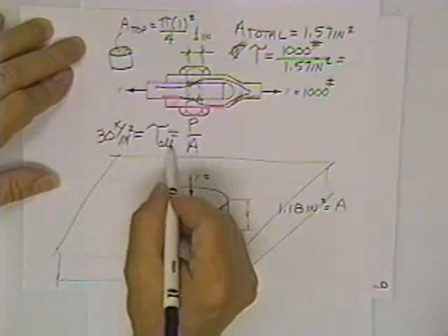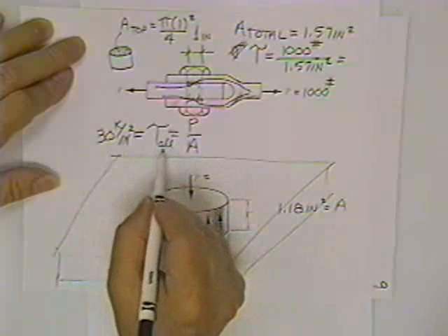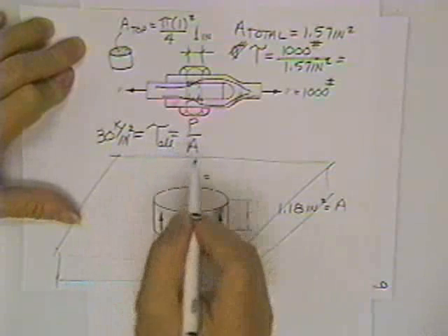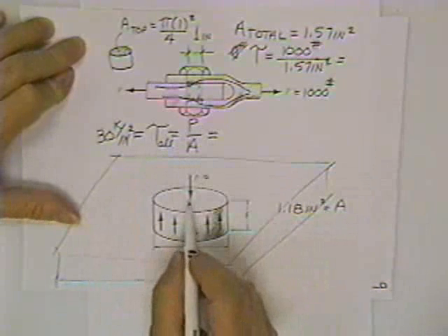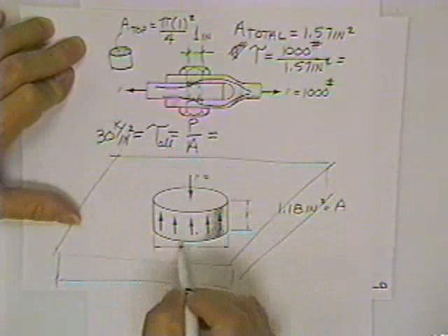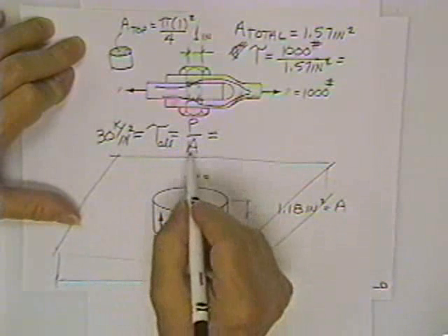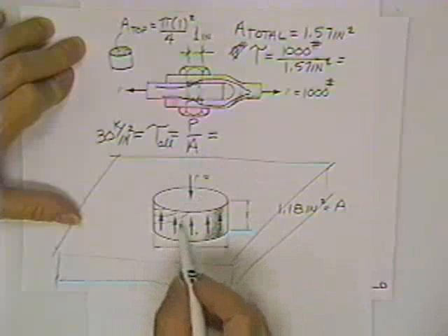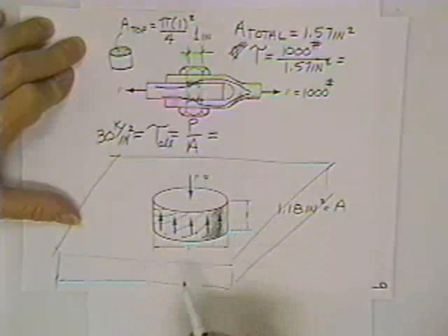Then I would put that allowed value or that failure value in my equation. The stress is load over area. I was asked how much load it took to punch this hole in the plate. So all I really need now is the area. Well, this is the area right here.